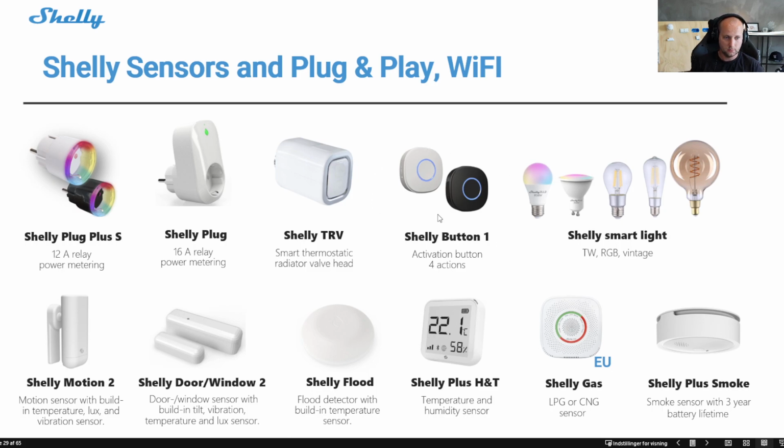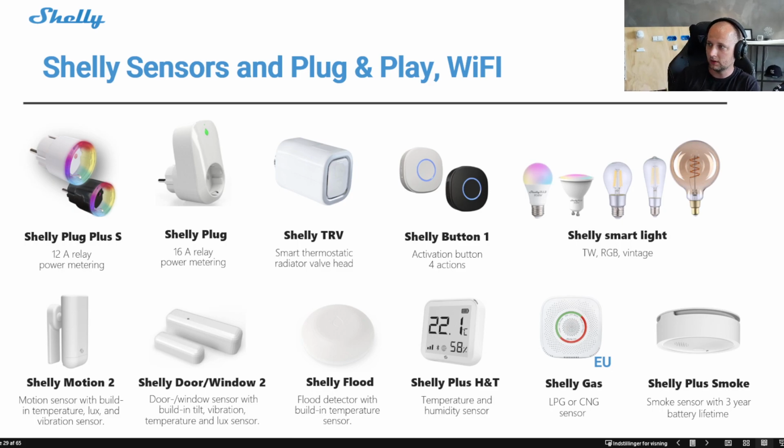We have the Shelly button 1, which is a small button here connected to Wi-Fi. The main issue with this button is that it is quite slow. So from you press the device, it takes 1 to 2, maybe even 3 seconds before the light will turn on. And this is because this is a sleeping device. To save power and battery, it goes into sleep. And when you press it, it needs to wake up, needs to connect to the internet, and then needs to send the command. So there's a small delay.